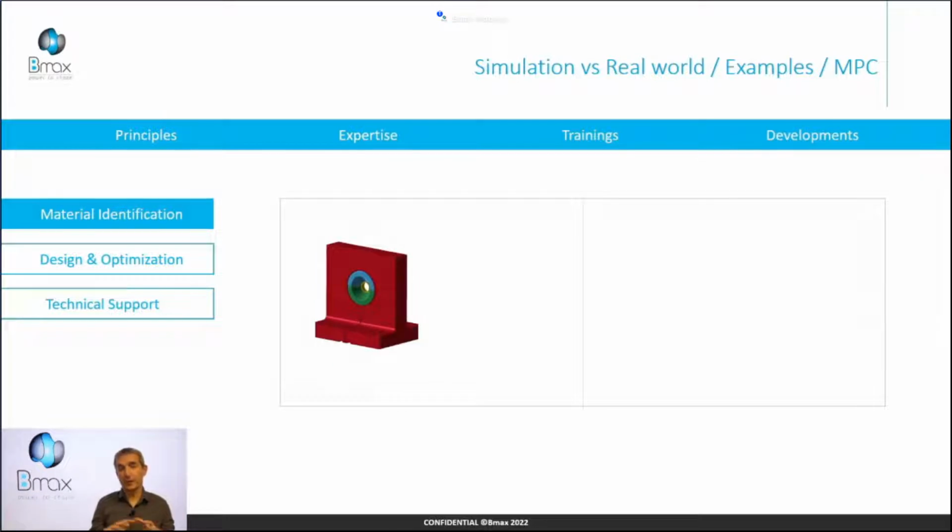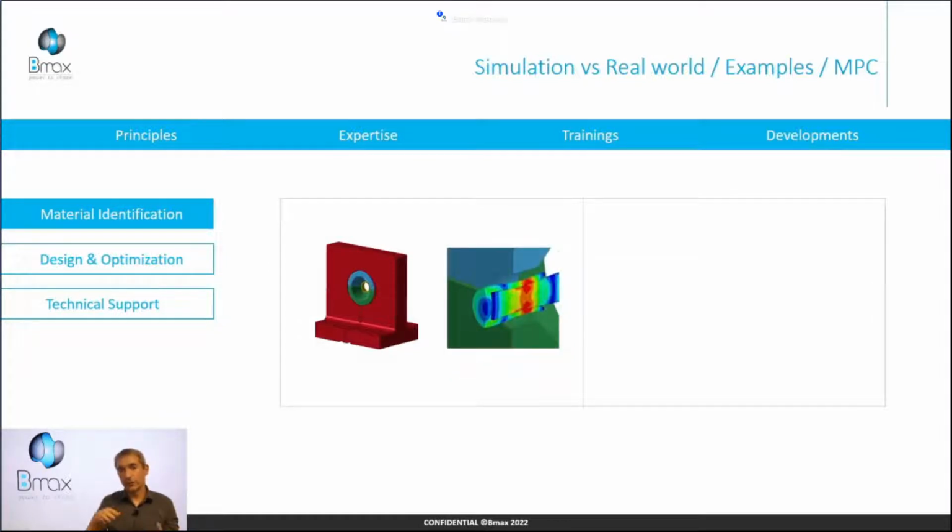First, we mesh and pre-process the whole existing setup, with a measurement of the current applied on the system. It's the first iteration. After, we change the geometry of the blue and green parts to reduce the ovalization. And after 5 iterations, we reduce this ovalization by a factor of 10 and the maximum temperature in the active zone by a factor of 2. It's a good point for the lifetime of this component.